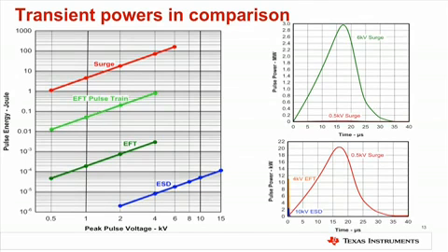Though an individual EFT pulse peak voltage is only 4 kV compared to the ESD pulse of 15 kV, an EFT pulse delivers more than twice as much power. Moreover, this test requires the application of 6 burst frames of 10 seconds duration with a 10 second pause interval between each frame. The entire EFT pulse train delivers 4 orders of magnitude more energy than the ESD pulse.